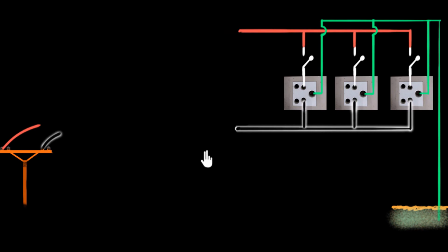but not always. That's right. You don't always get 220 volts because there can be fluctuations. You might know about this. There can be, say, lightning strikes or short circuits or overloading, things that we'll learn about in future videos, of course. But because of all of these things, voltages need not stay the same. Sometimes you'll end up getting low voltage, in which case your light bulbs and your tube lights will glow a little bit less. Your fans will be working a little slower, which is a minor inconvenience, not a big deal.